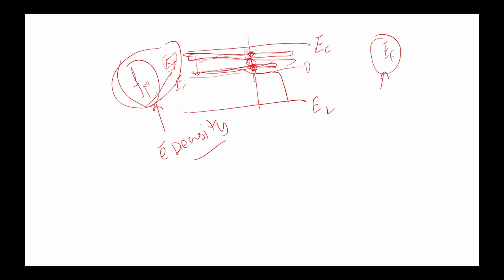So instead of finding the electrons in the conduction band, we are finding them at the traps. These traps are consuming our electrons and decreasing the charge density of the semiconductor. They are trapping the charges, so the current density J will be lesser if Et is near the Fermi level.